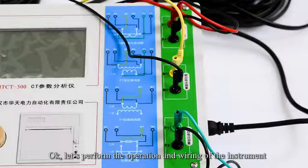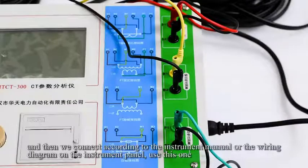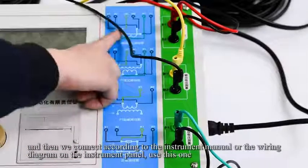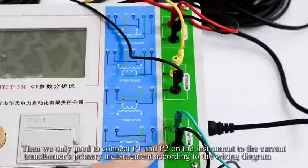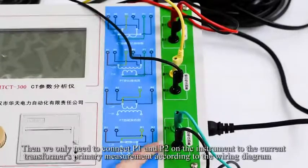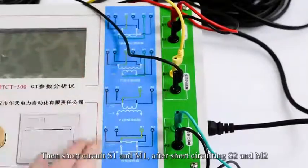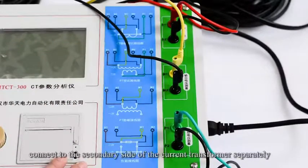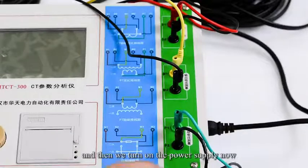Okay, let's perform the operation and the wiring of the instrument. We are using a current transformer, and we connect according to the instrument manual or the wiring diagram on the instrument panel. Then we only need to connect P1 and P2 of the instrument to the current transformer's primary side according to the wiring diagram. Then short circuit S1 and M1, and short circuit S2 and M2, and connect them to the secondary side of the current transformer separately. And then we turn on the power supply.